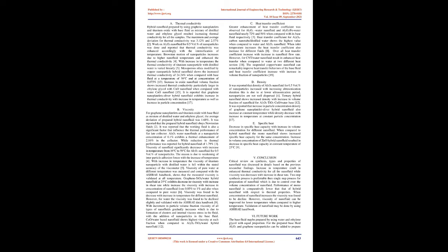10. Properties of nanofluids. In this section, properties such as thermal conductivity, density, viscosity, and specific heat of nanofluid prepared by previous researchers have been discussed in detail. Thermal conductivity. Hybrid nanofluid prepared by using graphene nanoplatelets and titanium oxide with base fluid as a mixture of distilled water and ethylene glycol resulted in increasing thermal conductivity for all the samples. The maximum and average deviation for thermal conductivity was 3.12% and 2.57%.